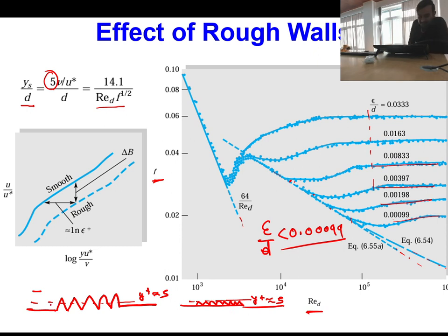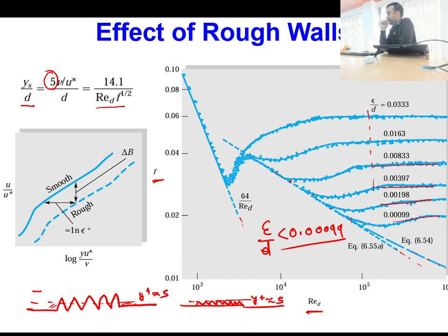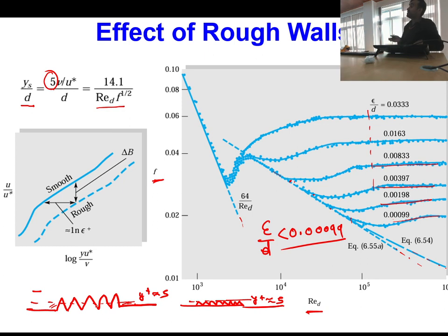On contrary, in this case what is happening? Viscous sublayer is there dominant, but that is lying within the roughness. Beyond viscous sublayer also some rough portions of the pipe are protruded. Okay, so in this portion the effect of roughness has to be accounted sooner. So that's why this roughness effect is actually transferring towards the low Reynolds number upon increasing the roughness of the pipe. Is this point clear?